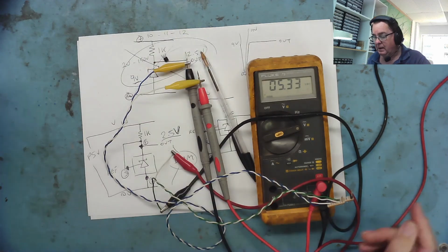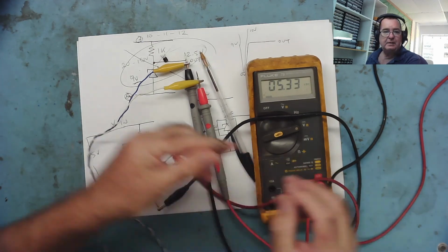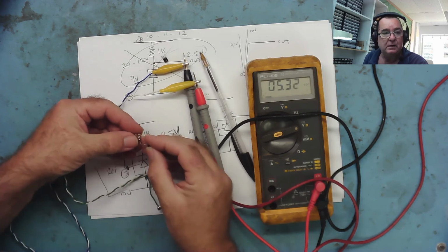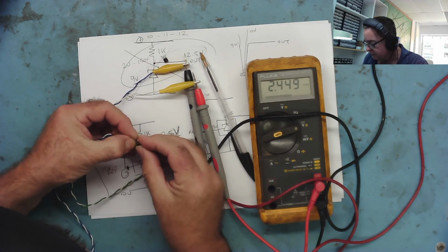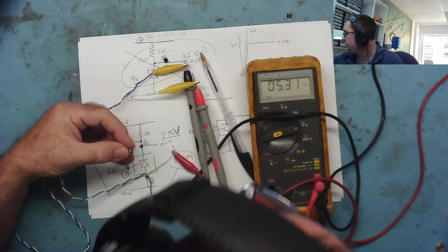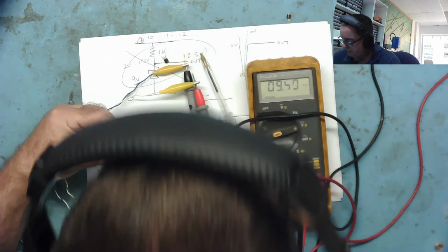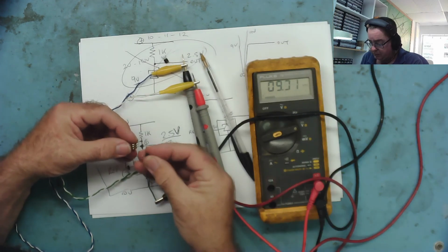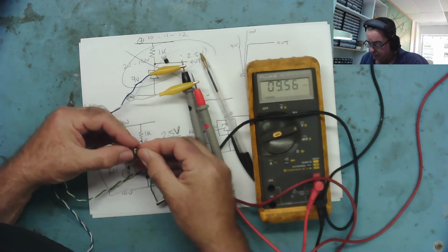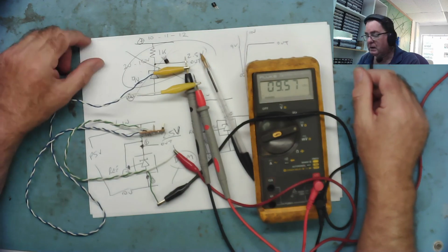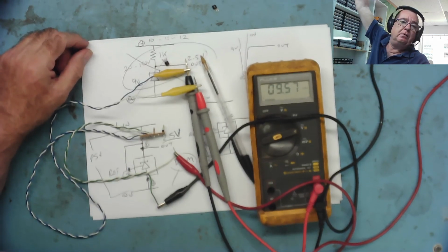That's handy. Last thing, let's just try this with a 9 volt input. Obviously then you could basically make one of these using a 9 volt battery, which would be very handy to have a portable little tester. Okay, so that's working. Let's take the voltage up to 9. It's close enough, isn't it? I mean, 9.5, it's close enough. Let's see what happens now. This should do the same. We should get the same reference voltage. 2.48. So yeah, you could build one of these using a 9 volt battery. Would be quite a handy little version of it.